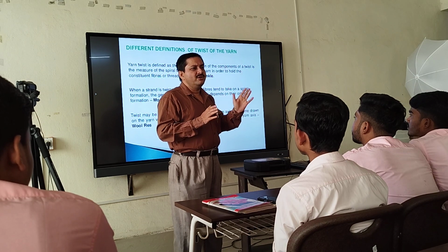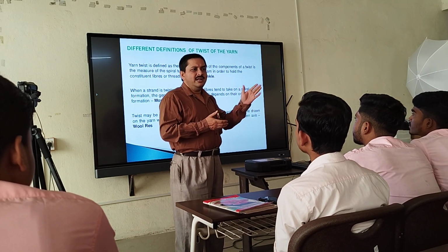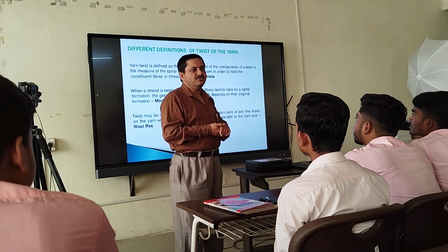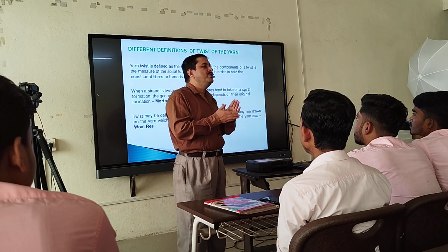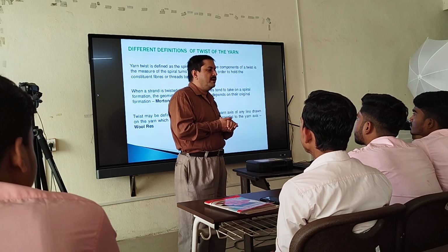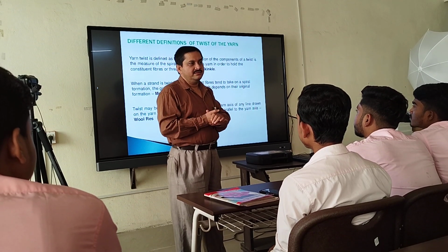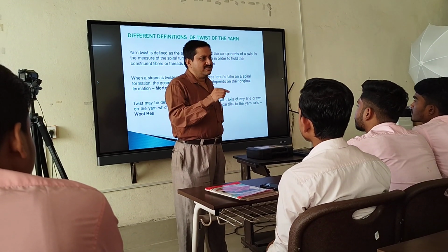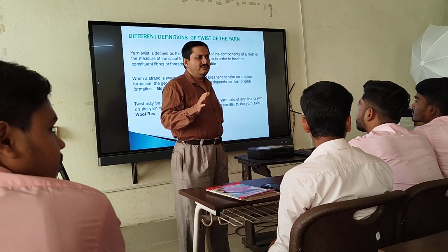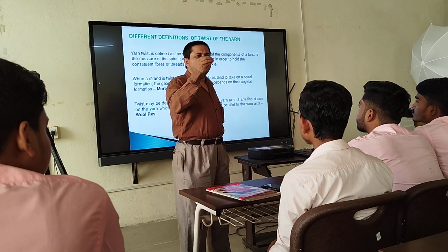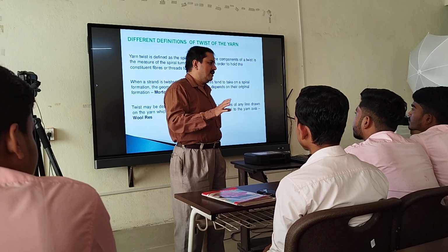In a word, we call this twist. In our laboratory, we measure twist as the number of spiral turns per unit length. This is turns per inch, turns per centimeter, or turns per meter. You can calculate this.